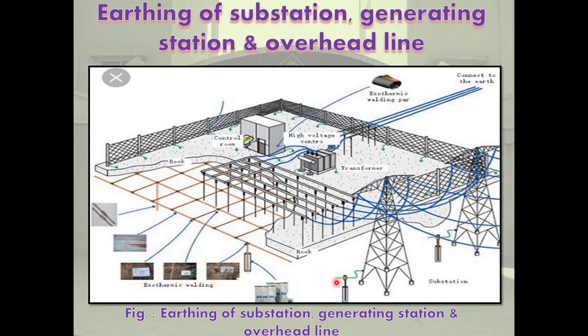Opening resistors are in parallel with the main breaker contact pairs. While opening the circuit, the opening resistors open first, thereby the switching surges on opening transmission lines are reduced in magnitude. Surge arrestors are placed between the phase and ground near the breaker terminal on the line side.